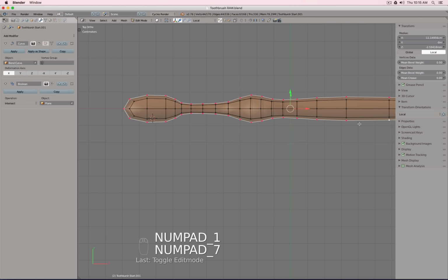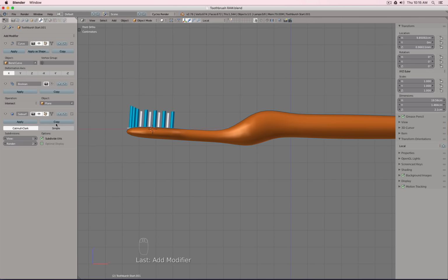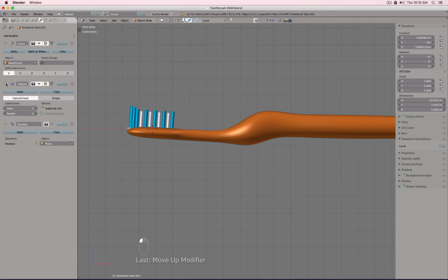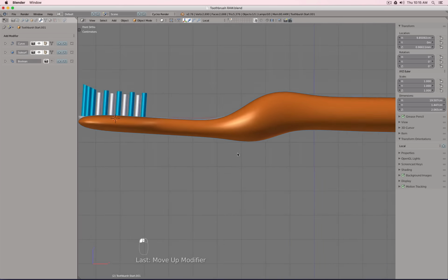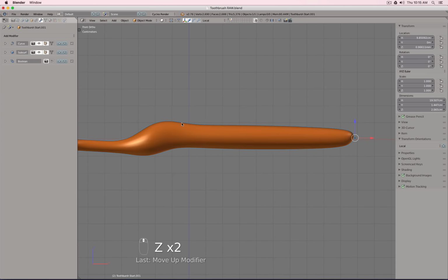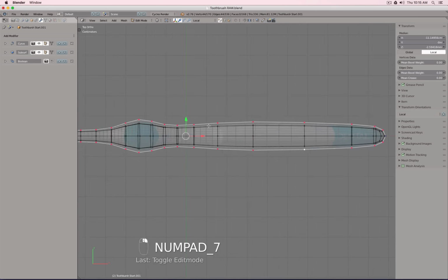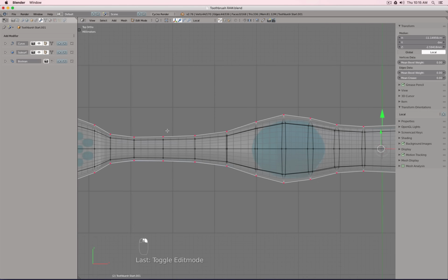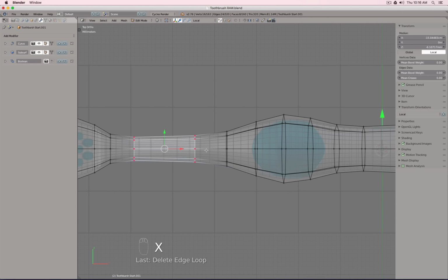So we can see if there are too many points, or maybe I have to loosen everything up a little bit, so I reactivate my curve control and bring back, for example, a sub D modifier. The Boolean is still there, but I can turn it off for the moment. And let's take a look. Essentially, you always want to have the least amount of geometry as possible, because it simply is less work for you. So maybe this loop cut, I don't really think I necessarily need.